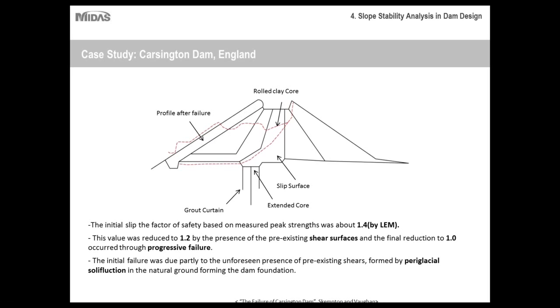Obviously it had a winter and a summer, and over those periods of time when the water in the pores of the dam was frozen, it created additional shear forces acting in the dam. As you can imagine, when water freezes, it expands. So just imagine all of the water in this dam expanding over the course of a winter. That will cause some breakage or some shear forces within the dam.